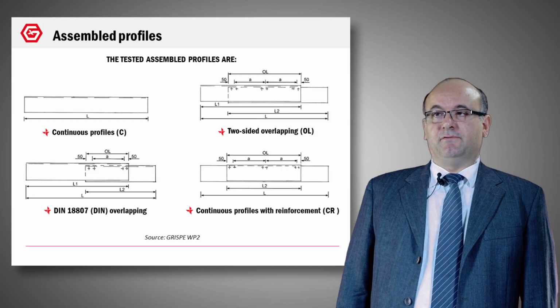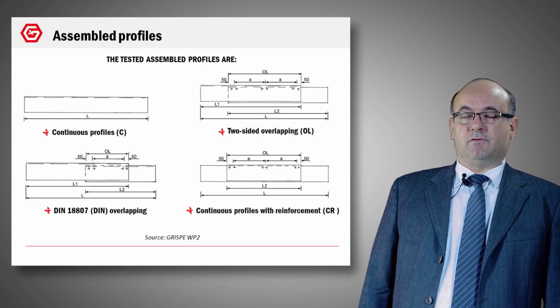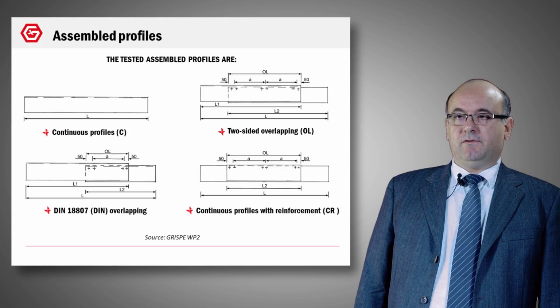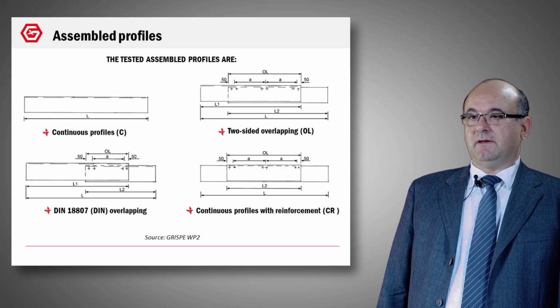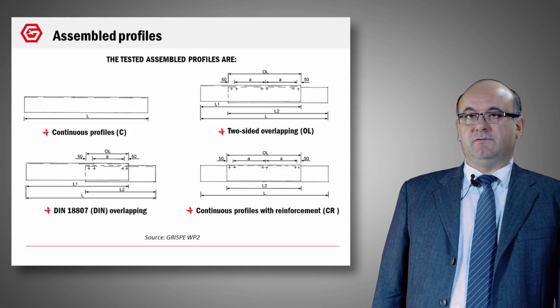To do that, 4 tests were done. The first test was done on a continuous profile, which serves as reference, and 3 other tests were done on the overlapping, on a 2-sided overlapping, and on the continuous profile with reinforcement, to obtain data to calibrate the design method.